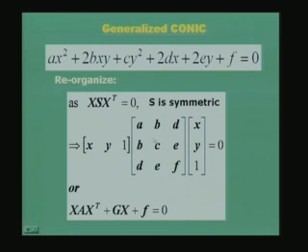And this has to be there because S is a symmetric matrix; A, C, F are the diagonal terms. So the non-diagonal terms, or the off-diagonal terms, in this symmetric matrix must duplicate themselves to give the symmetric nature of the matrix. If that is so, you require 2 of these off-diagonal terms, which are B, D and E, and hence that is the reason why we use that factor 2 in that quadratic form. That is the answer to my question which I put at the beginning of the class today, why these 2 could be used.